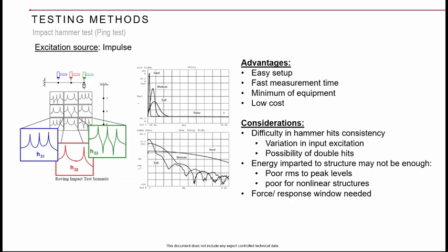Similarly, the other case is when you have nonlinearities, like contact nonlinearity. For example, you take an actuator itself, where you have a cylinder and piston rod with certain seals in the middle. When you go with impact hammer test for such a scenario, the frequency that you get through the test will be very low, because the whole system frequency is not established because of the contact gaps.